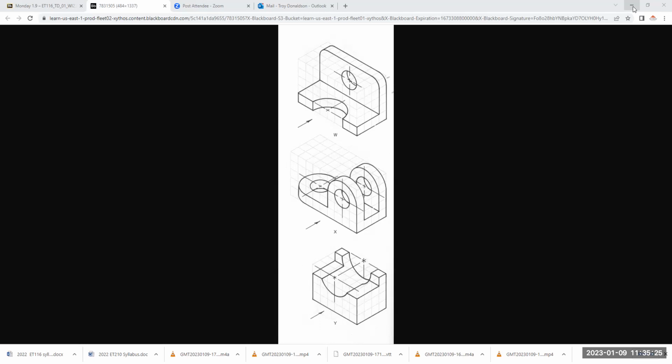Yeah, I mean, it looks a little small, but that's because I'm zoomed out. Like if I move in, it doesn't look too bad. That'll work. So you've got to have your drawing done before you dimension, at least know how much space you're going to need, and then figure out this scale, 1:5. Now I can go back to model, and you'll see there's an annotative scale right there. That's what you want to set to 1:5.